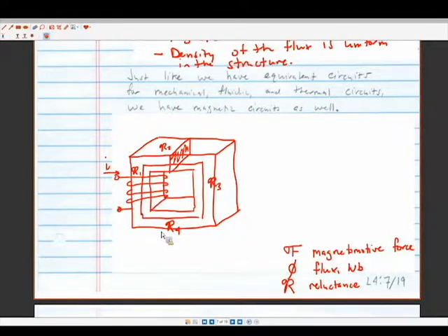And then I'll bring in some motors too, and you'll see that the gaps between these ferrous structures are quite small, on the order of a millimeter or two. Because the reluctance of the air gap is really large, and that makes it less efficient. And you can't make it too small that they're hitting each other, either, because that would be mechanical inefficiency.